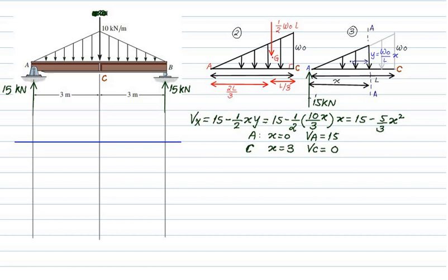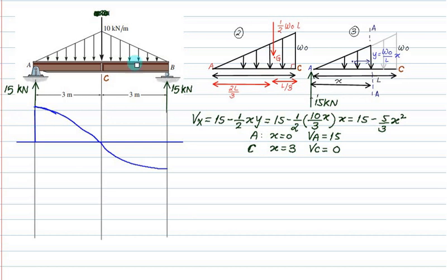The shear force diagram is proportional to minus x square, a downward parabola. The downward parabola will be like this. The left hand side will not come in the picture. So this is a parabola of second order degree, and finally we close at 0. So this also equals minus 15. So we have degree equal to 2.